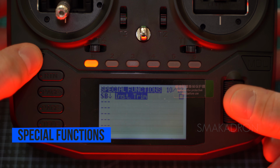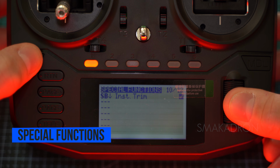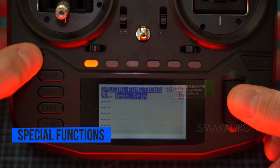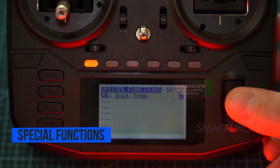The instant trim function allows you to quickly and easily adjust the trims on your transmitter. This function automatically sets all trims to the current values of their corresponding sticks. This is very useful when you want to quickly trim a model for stable flight or when you find that your sticks are slightly off-center and you want to save the current position. For our FPV drone, this function is not needed.